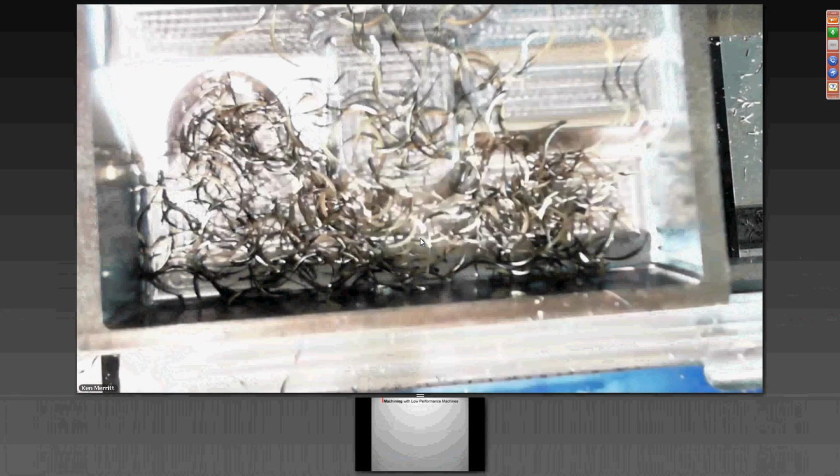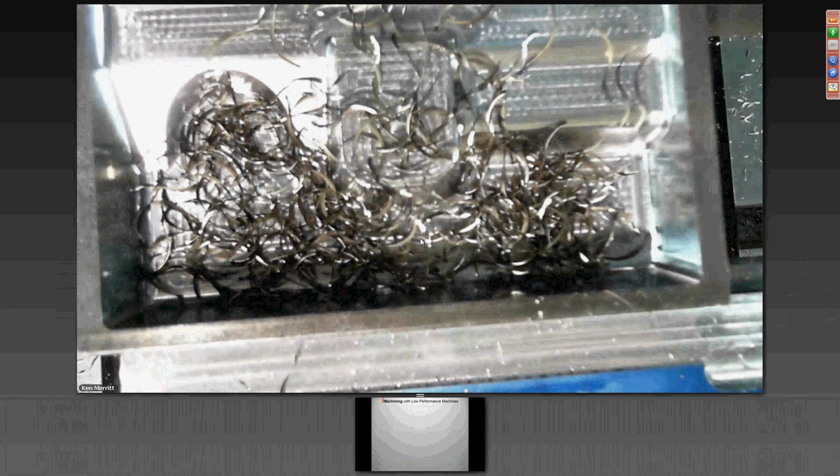But as you can see from those chips, you can see a real consistency in the chips. And this is really important, because this is our feed rate advance. As that angle is changing all the time, we're continuously moving the feed rate back and forth so that the chip thickness remains the same. What that does for you is that keeps a very, very constant load on the tool. So this tool is not seeing a lot of shock.